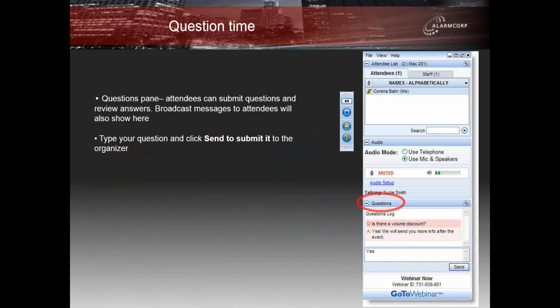Next question. I have seen cameras with a DWDR feature. What are these? DWDR, or digital wide dynamic range features, are not the same as a true WDR camera. They may have some additional circuitry over a standard camera, but they will not perform to the same degree as a fully compliant WDR camera. It is basically a manipulation of the digitized picture in the camera. It may appear to make the image look better, but the extra detail will not be there. The cost for these types of cameras should also reflect that.